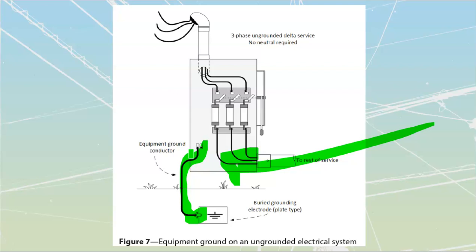Last section of the module talks about bonding conductors. Although we talk about conductors and it's usually wire, there are other things that are allowed to be our bonding conductors. If you go into section 10 of the CEC, you're going to find out that we can use conductors. They can be insulated or they can be bare. So you can have the green coating over top of them or they could be just bare.